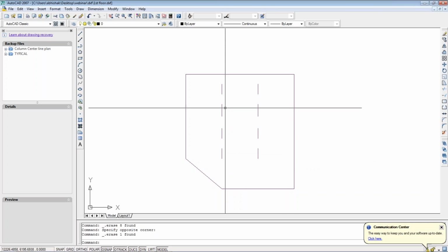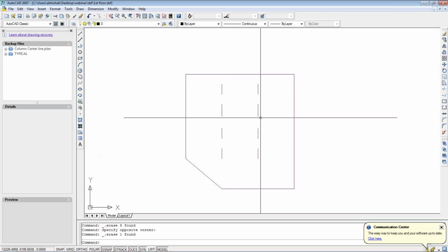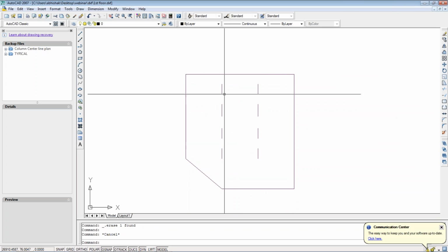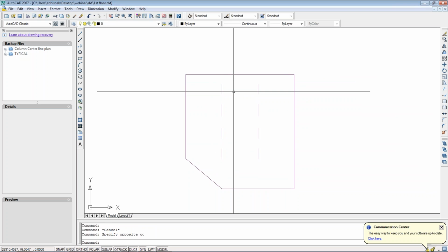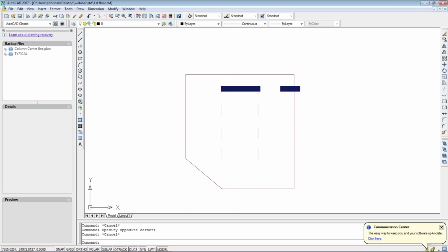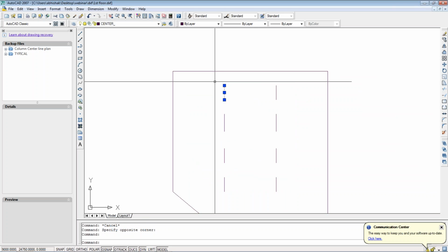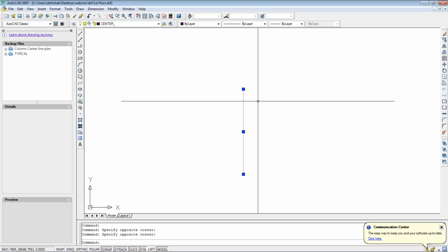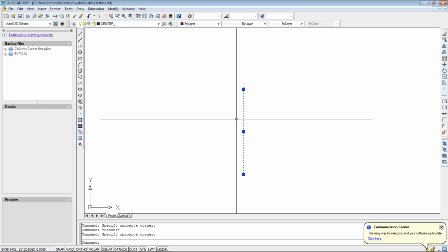So you can directly import this line as an AutoCAD DXF. This area is totally flat slab, and this particular beam also you can import. At the joint of this particular beam, at this particular node, you can directly get it from MIDAS Gen. Then you can delete this beam.